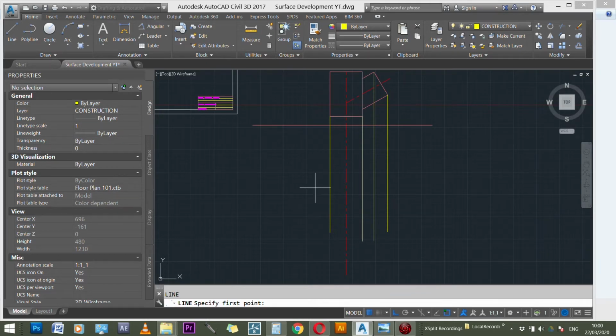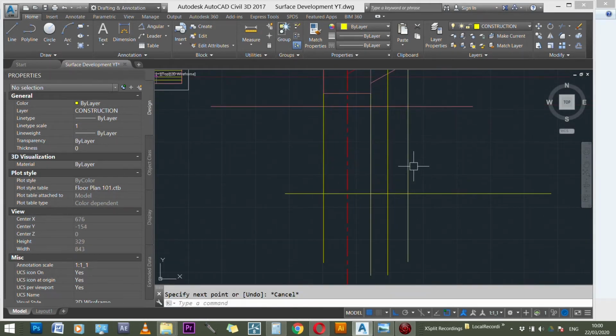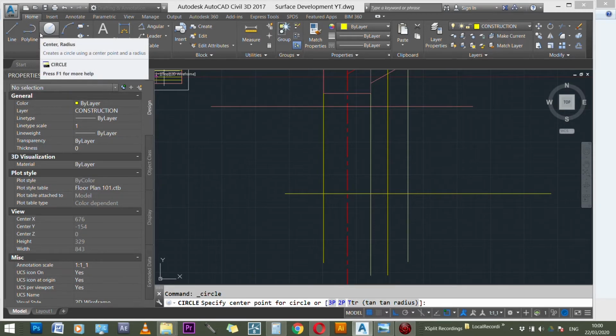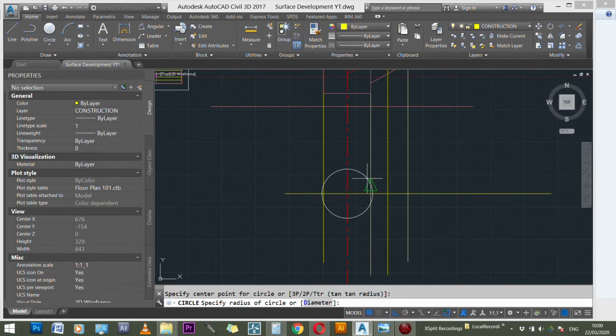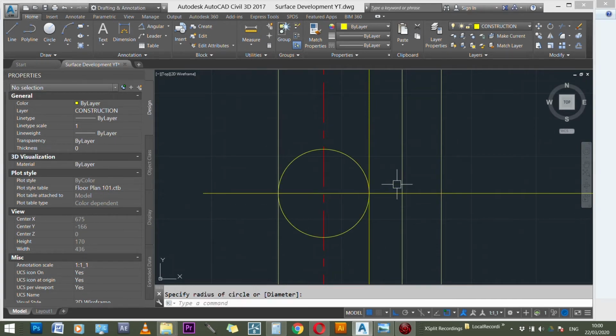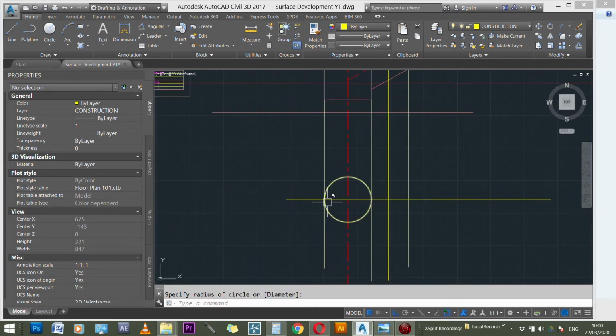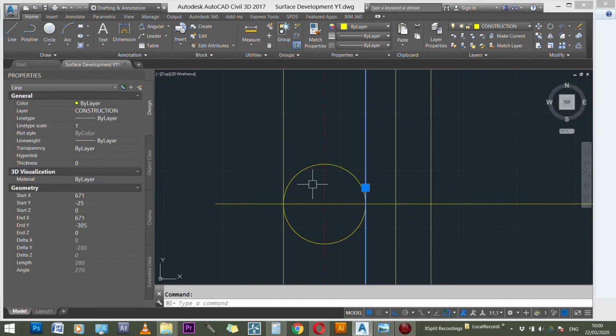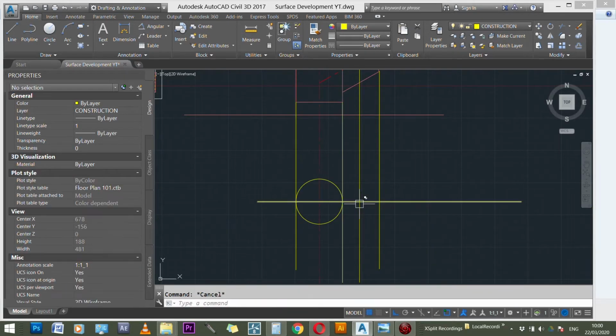What I'm going to do is we need a horizontal line, just randomly put the horizontal line there. Go on to the circle layer, activate your circle command. You can just go over the circle and you will get a circle, or you can hit C for circle. Open up my circle, and the extent of my circle is radius 35. Or I can just bring it to these boundary lines, it doesn't matter. I can type in 35 radius, or just bring it to one of these boundary lines which I have carefully set up.